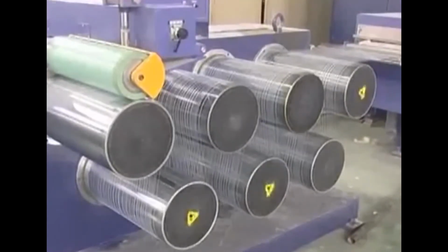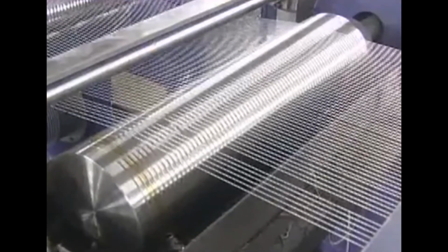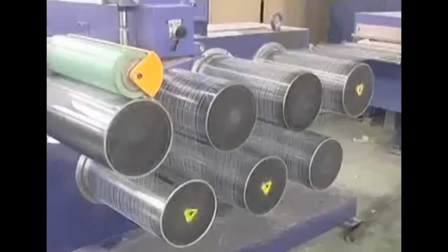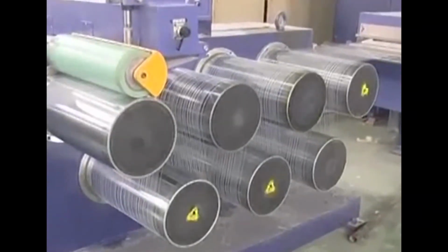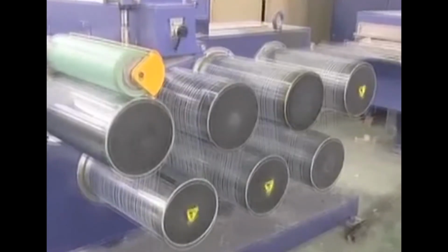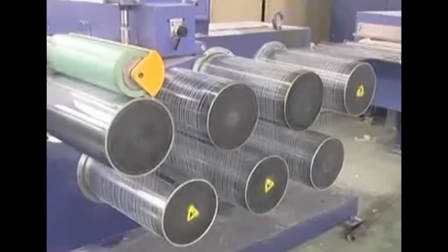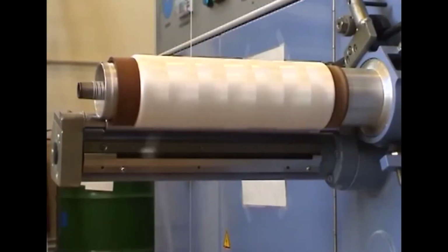So, when the filament is fed through it, the second one will pull it 4 times more than its length, and thus it attenuates the filament and also aligns the molecular chains to the fiber axis. And thus the filament that comes out is wound on bobbins or whichever package they want, and then taken off from the chemical spinning.